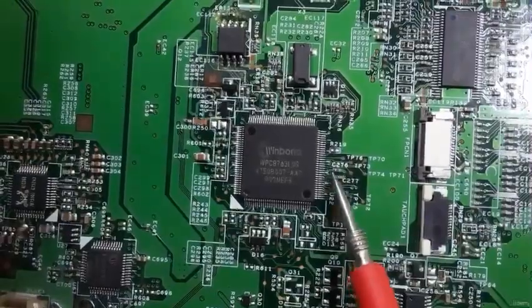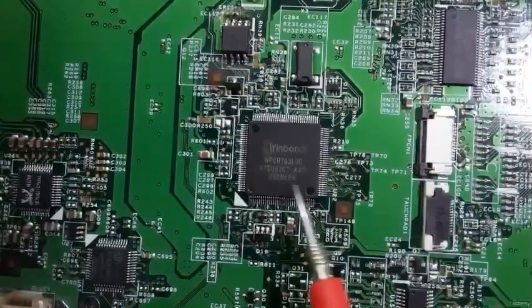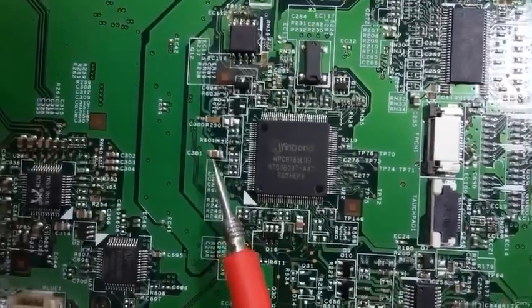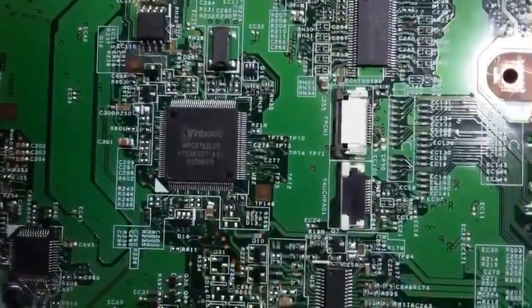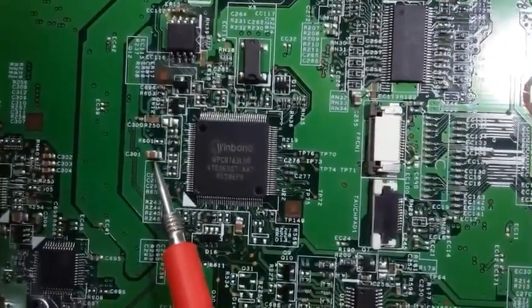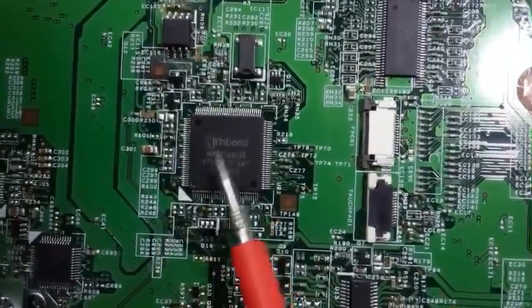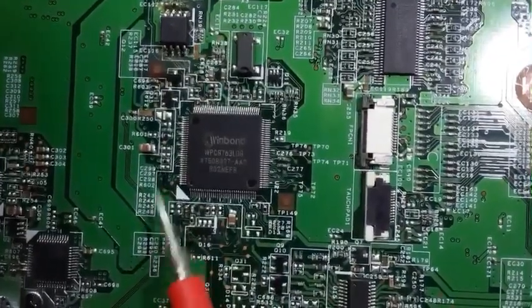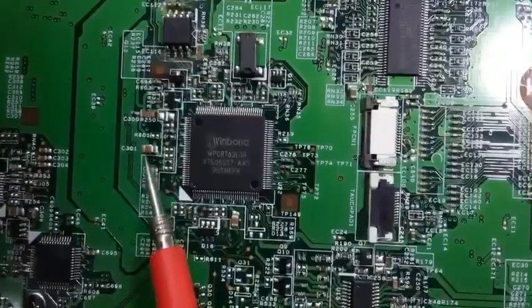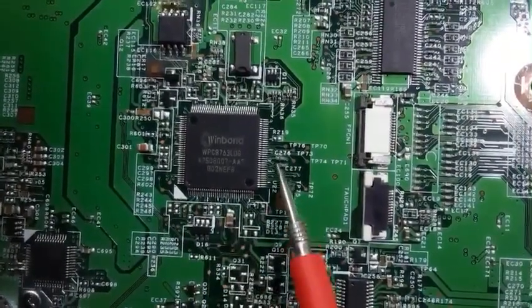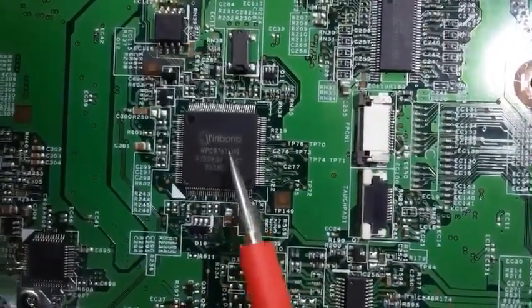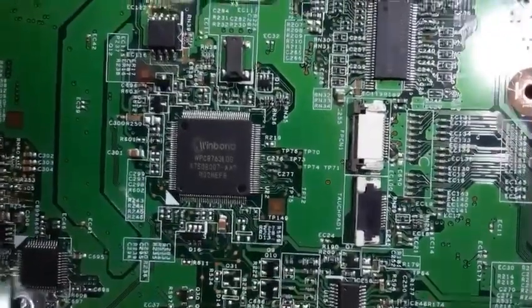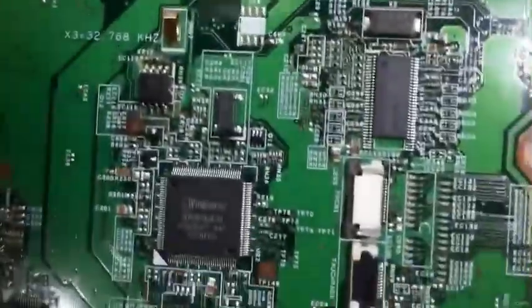This one also, as you can see here, and this one also, because if you find any one of these shorted to the ground, means this IC is shorted to the ground, because always the PF capacitors or the ceramic capacitors near this IC are connected to the power rail, not to the ground. If you find this or this, for example, connected to the ground, means this IC is short. Let's check these PF capacitors using the multimeter.